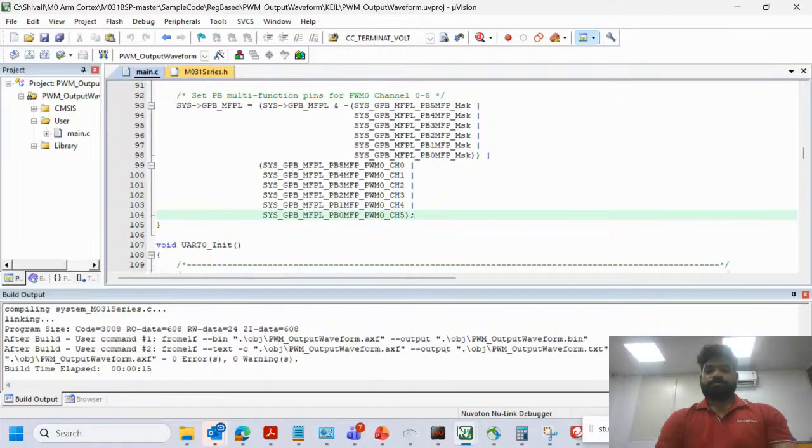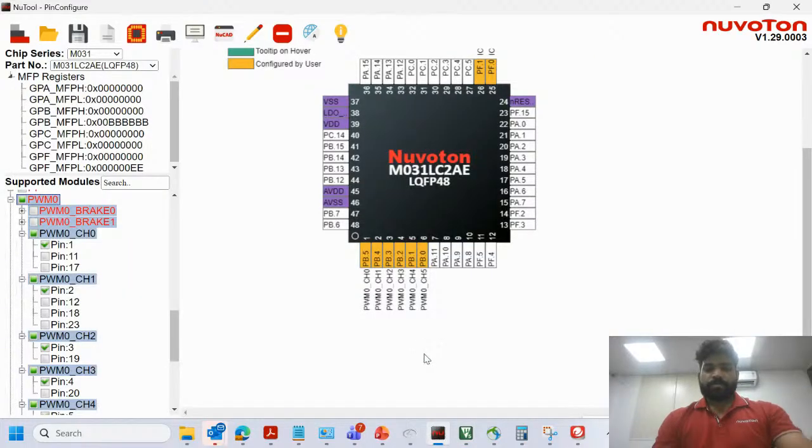Now, as you can see here, PWM channel 0 is on PB5, PB4, PB3, PB2 and PB0. So these are the PWM channels, PWM0 group, channel 0, channel 1, channel 2. But now I want to add one more channel from the PWM1 group.